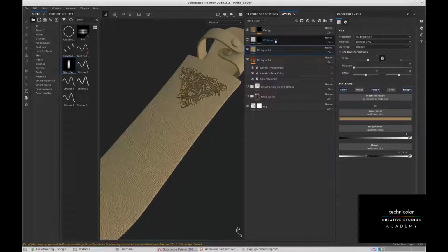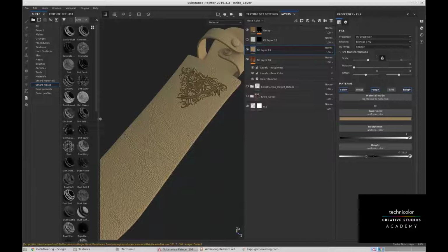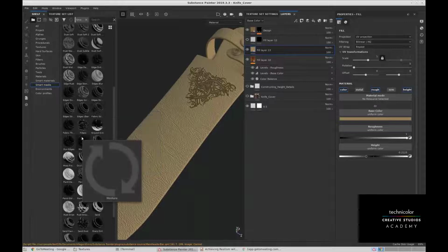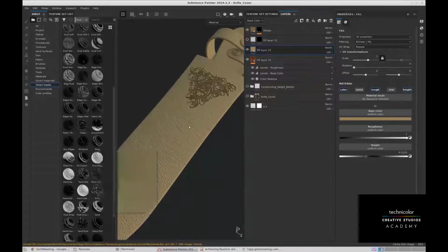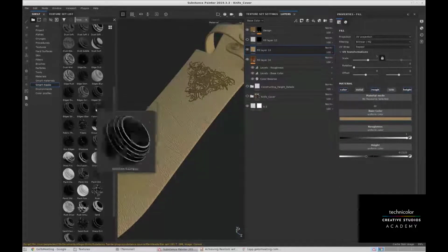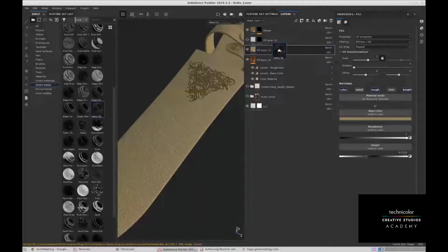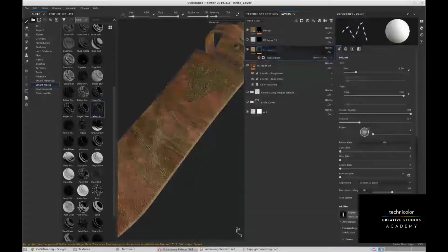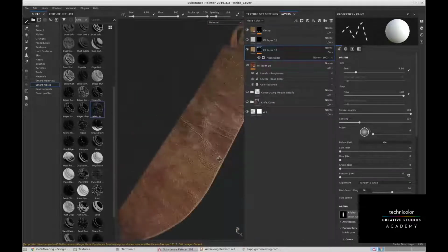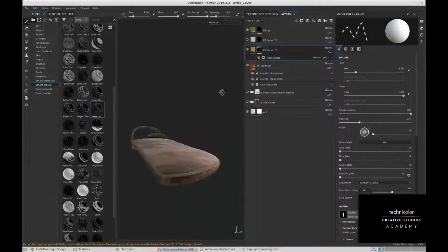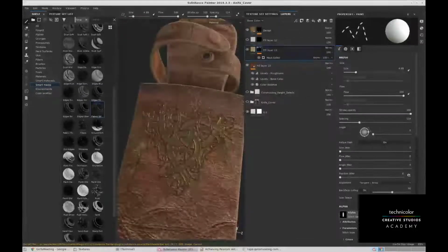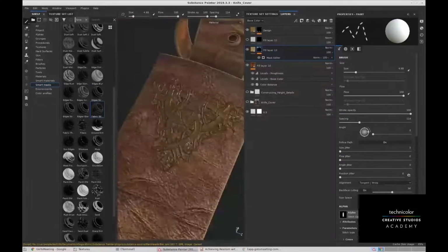So now the smart masks. How the smart masks work, you will know. So select the smart mask carefully according to the material you're using. So we will use a fabric edge damage smart mask on the top of it. Just drag and drop it on the layer. See? So we can see it's working on the top of the mesh, only the model, not on the displacement details or height details which we have made on the surface.